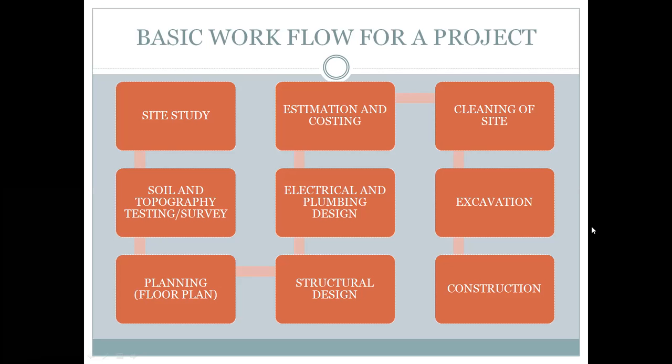First thing that you're going to do is the site study. Once you do the site study, you will get to know what the water availability there is, what the type of soil over there is. That is basically the dimensioning, the surveying, where there are more depths, if there is somewhere you need to excavate, if there is somewhere that you need to cut or fill. So all these things you need to study in the site study.